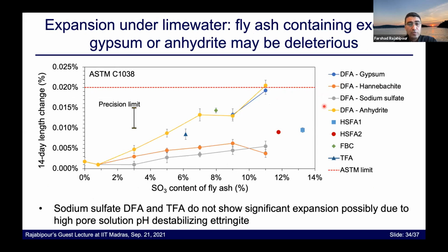Finally, I want to show you the so-called expansion under lime water. This is ASTM C1038. This is a test that is looking at whether the excess sulfate, or excess SO3, I should say, can cause ettringite formation and volume instability in mortar, and by extension in concrete that is exposed to water. So you make mortar bars, you cure them under lime water for 2 weeks, and you look at expansion.